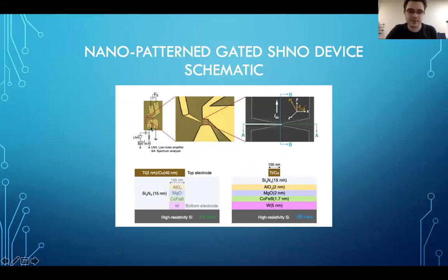And these bottom 2 contacts are used for sending current. This current passes through the beta-phase tungsten. Beta-phase tungsten is known for its high spin orbit torque to create spin currents at the interface. And this axis represents Y upwards, X to the right, Z is out of plane. Phi represents the in-plane angle and theta represents the out-of-plane angle of the H. And also microwave signals are measured from this bottom contact.